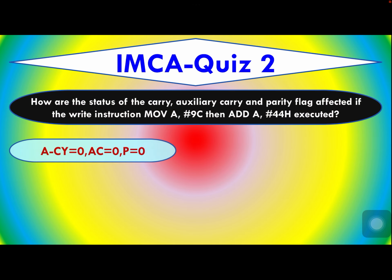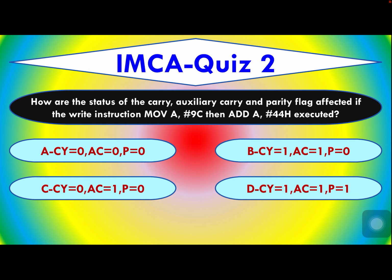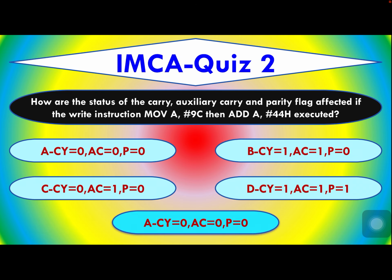How are the status of the carry, auxiliary carry and parity flag affected if the instructions MOV A, #9CH and then ADD A, #44H are executed? A. CY equals 0, AC equals 0, P equals 0. B. CY equals 1, AC equals 1, P equals 0. C. CY equals 0, AC equals 1, P equals 0. D. CY equals 1, AC equals 1, P equals 1. The correct option is A. Carry equals 0, auxiliary carry is 0 and parity also 0.